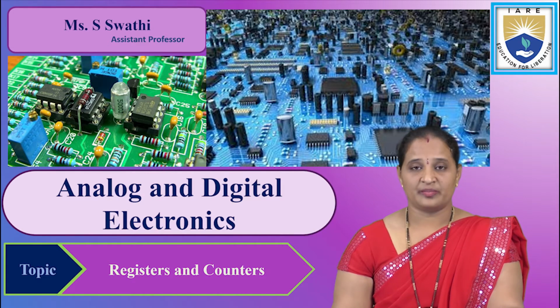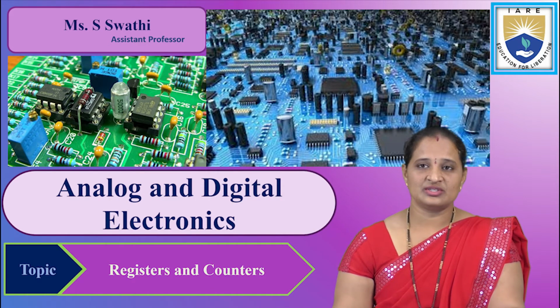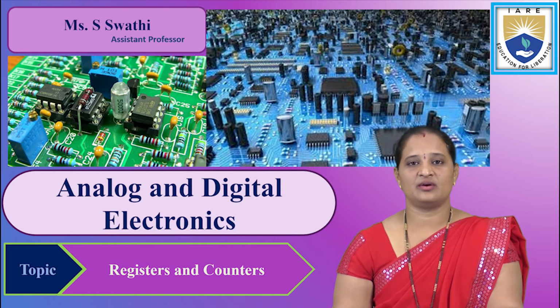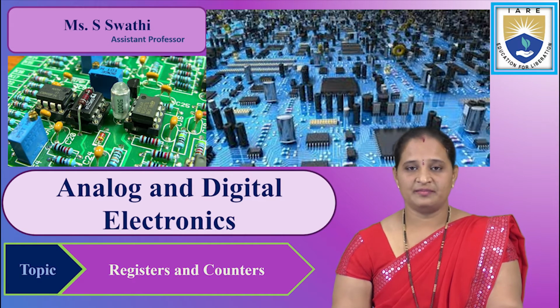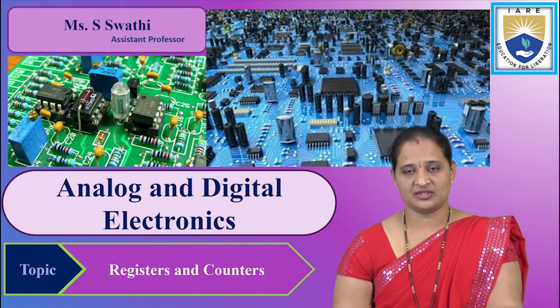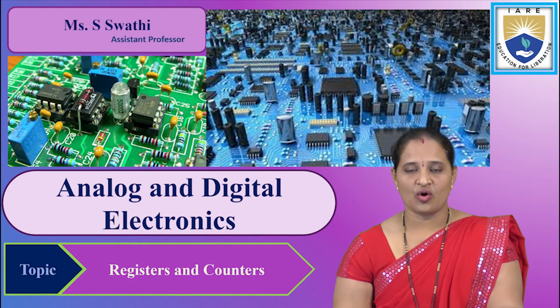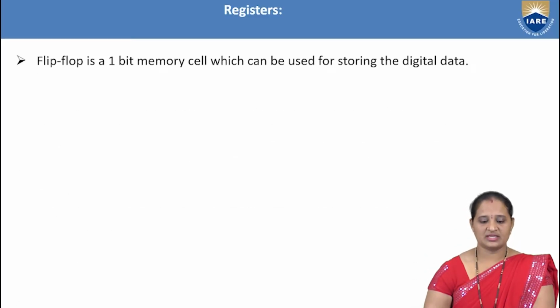Welcome to today's lecture. In this lecture, we are going to discuss registers and counters. We'll be concentrating more on registers and the various types of registers, that is the shift registers, and various modes of operation of shift register, and also universal shift register. So first of all, what is a register?